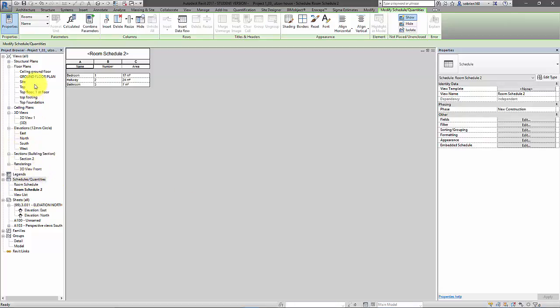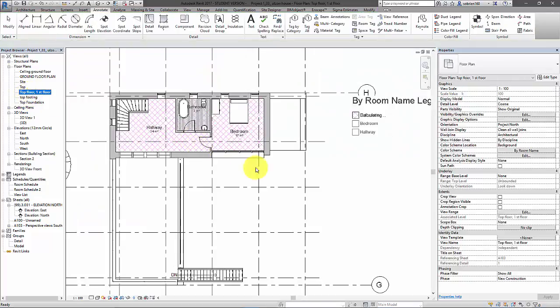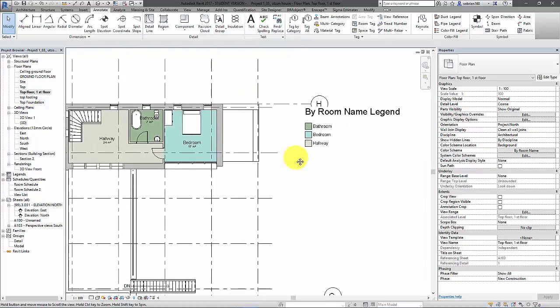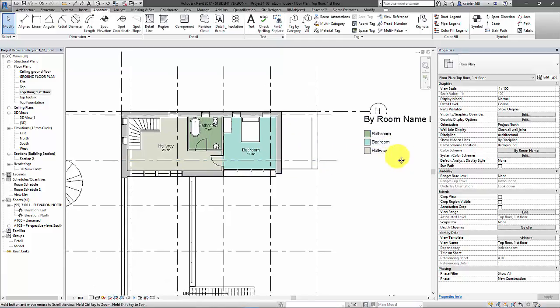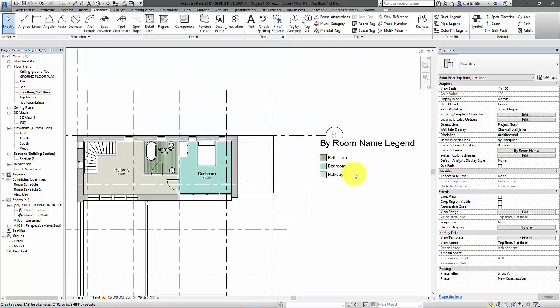Okay, there's some confusing stuff in this project, so we won't worry about it too much. But anyway, what this should be doing is just straight away giving. There it is. Now it is. I think you might have some errors in the project. So next time you open it up, audit the project because there's an option to audit it. Audit will go through it and find some errors in it because it seems like there's quite a lot of errors in it, which generally gets caused by people just playing with it that don't really know how it works.